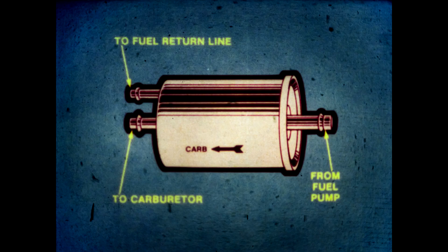The fuel filter is also part of the fuel return system. It has an outlet nipple that connects to the fuel return line, which is connected to the fuel tank sending unit. During normal operation, when underhood temperatures are high, fuel in the heated steel line between the fuel pump and carburetor can boil and vaporize. The fuel return line does two things. First, it allows constant fuel flow, which helps cool the lines and reduce vaporization. And second, if vaporization does occur, the vaporized fuel returns to the tank and is not passed to the carburetor.